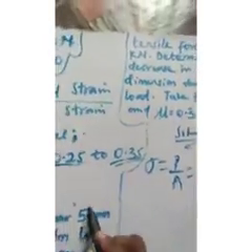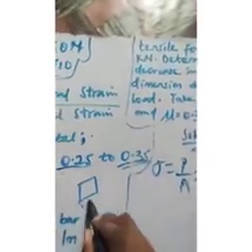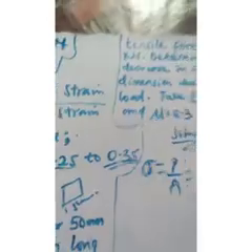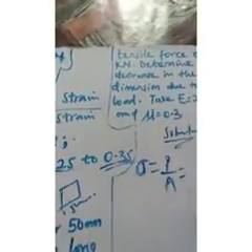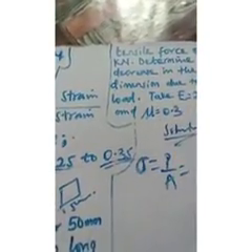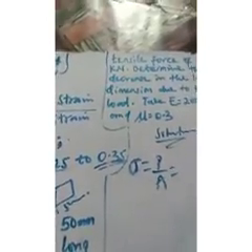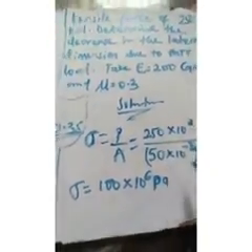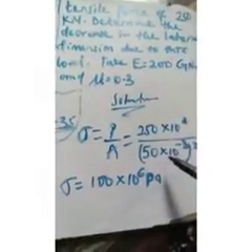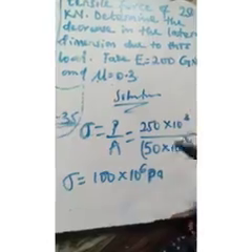So from here you find that the square steel is 50 millimeter. If you're writing this, I want you to suspend, just for a few minutes, and solve this, okay? If truly you solve it, you find you have to be very careful with this value. You tend to make small mistakes because your formula for area is pi d square over 4.